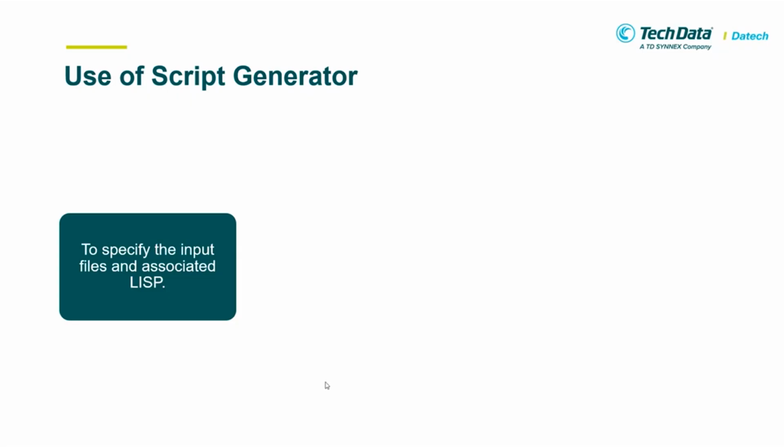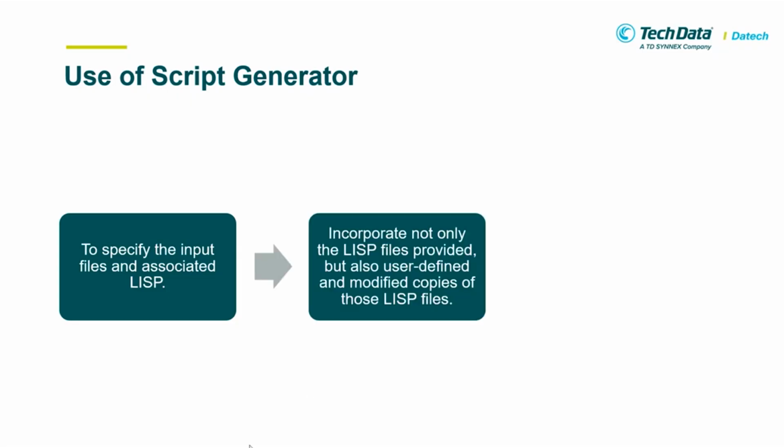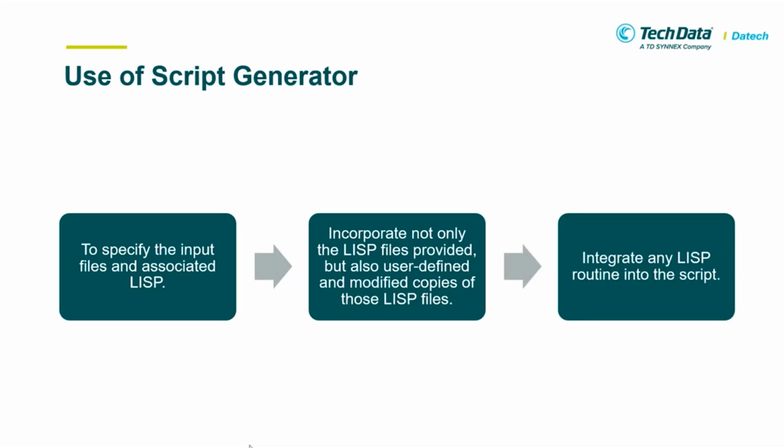You can incorporate not only the Lisp provided with AutoCAD, but also user defined and modified copies of those Lisp files. You can integrate any Lisp routines into a script. AutoCAD Mechanical Toolset includes built-in routines which are useful for exchanging a block, editing configuration, layer conversion, and much more.